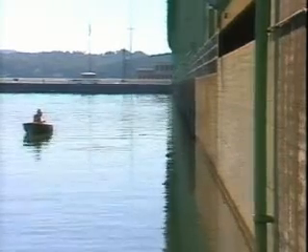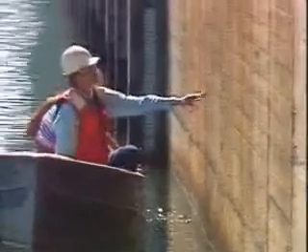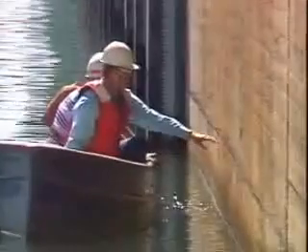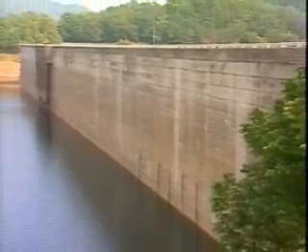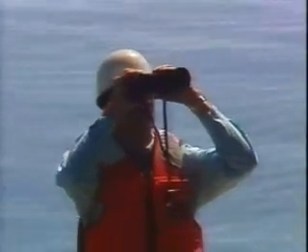Look at the face and abutments from a distance and close up. Also, develop a system for inspecting the face that allows you to examine all of the exposed surface. If you examine the upstream face through binoculars, follow a systematic scanning pattern as you did with the downstream face.